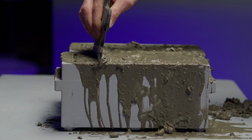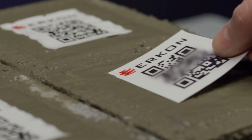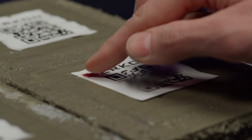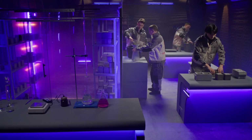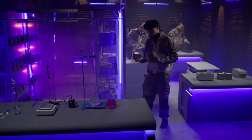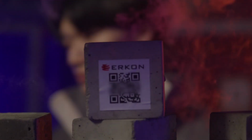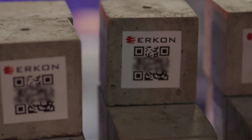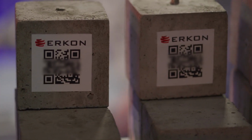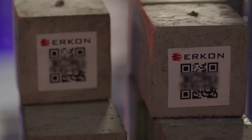Several cube-shaped samples are prepared from the concrete mixture, like these ones. Then they are kept in molds for a day, taken out and placed in a humidity-curing cabinet. After that, the fun begins. The cubes gradually ripen. They are like apples filled with juice and become strong. The cubes are tested on days 3, 7, 14 and 28.